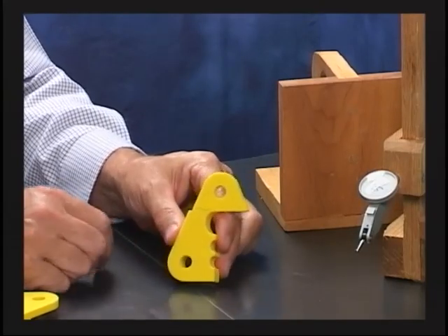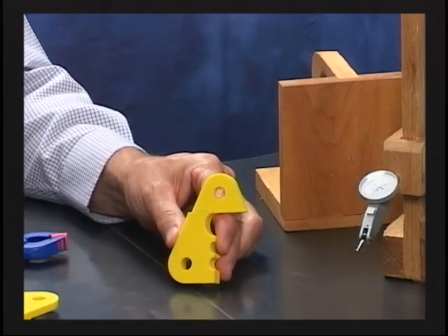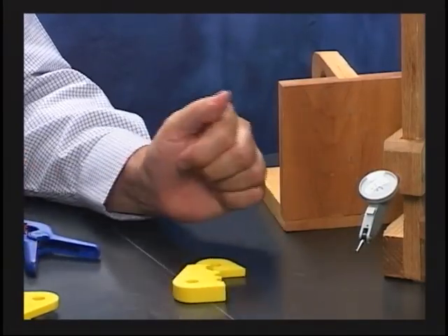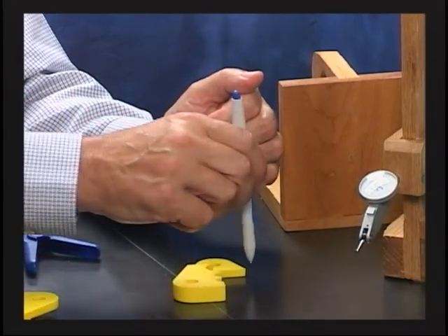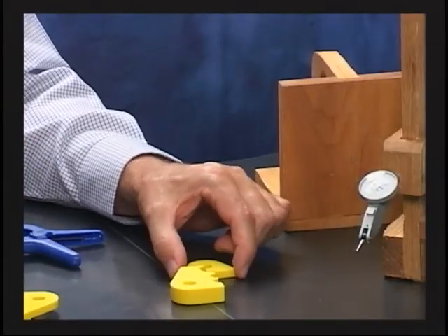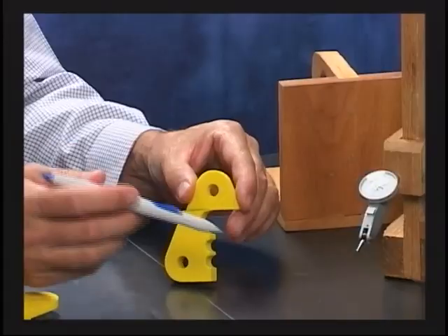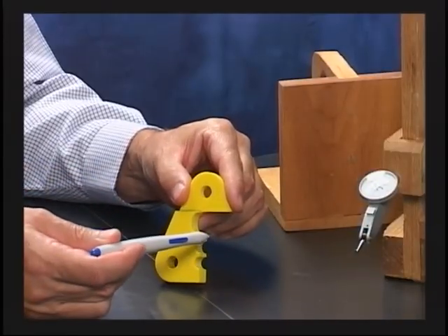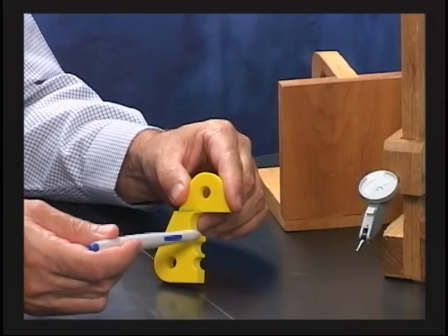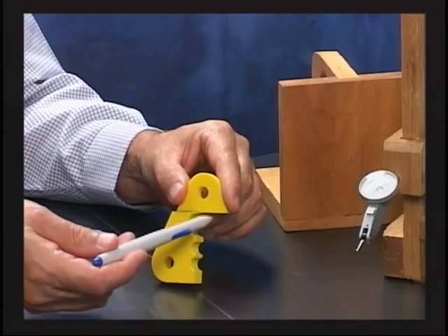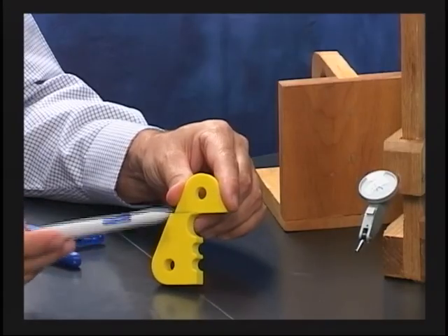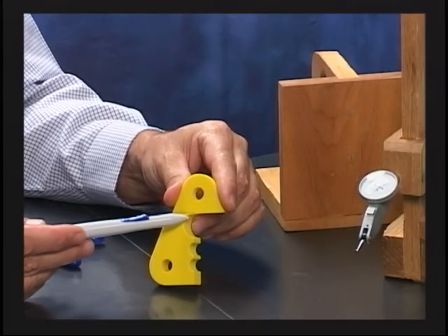Now, if you're going to measure this thing with a coordinate measuring machine, probably what they would do on something like that, well, I don't know, they might just lay the thing down on the table. If they came down on the table, I would touch my 0 on this back face and establish a plane. Once I establish a plane, now I have to come in with my secondary datum. Probably what they would do to establish the secondary datum is touch the surface a minimum of 2 points. You probably have to touch more than 2 points to establish a plane, and then touch a minimum of 1 point to establish a plane. And then once they did that, they would find an origin just like we did here a minute ago on the angle plate and surface plate.